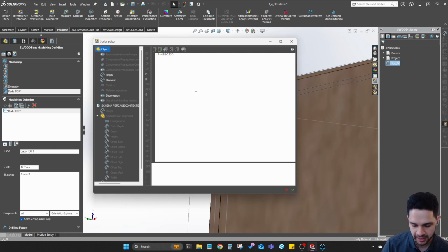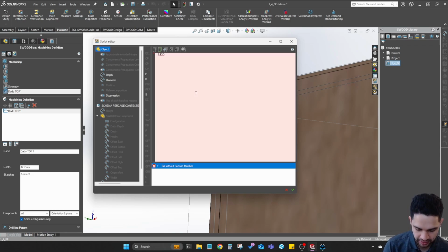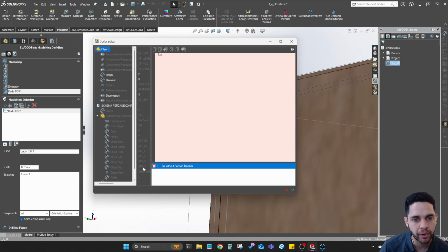So instead of it just being like DD, if I did just DD, it's going to have that red window error, no signification for the word DD. So oftentimes, if you're like, oh, I know I made that alias DD, look for it in this dropdown, and oftentimes there could be a prefix associated with it, and see, no red window.